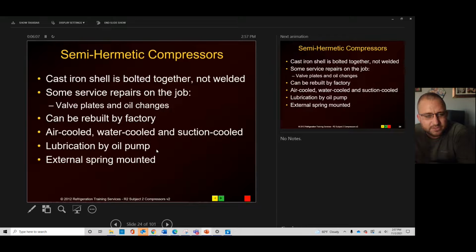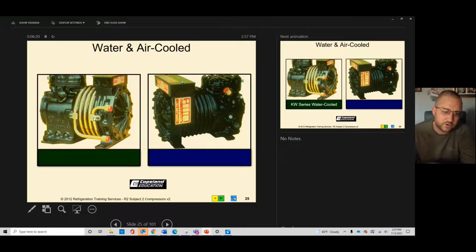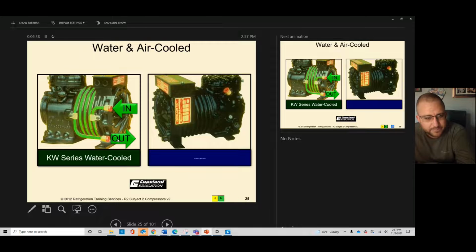These you'll see on a lot of different variety of equipment. Sometimes on coolers and stuff, you'll see these. There's different versions of those. So you can have air-cooled or water-cooled versions of those. So water-cooled would actually have a water jacket or a water loop going around it to cool it. That might be used in a place where maybe it's around a lot of heat. It's down in a mechanical room where it's very hot, something like that. It's obviously not going to probably be out on a roof that way, but a little bit different.